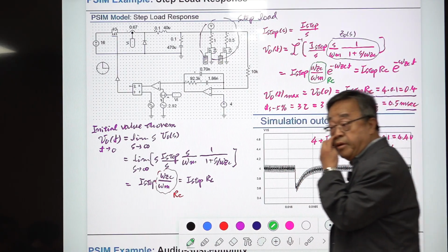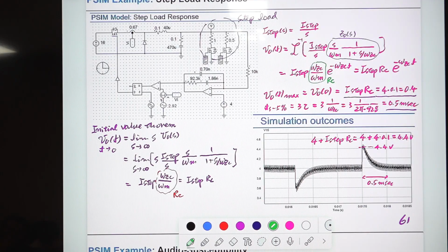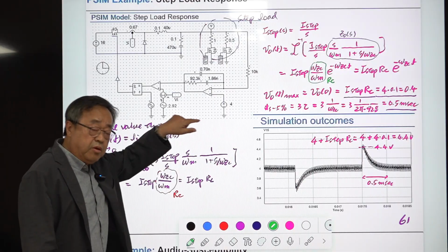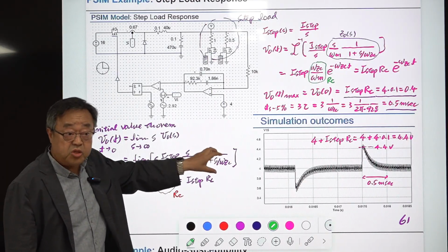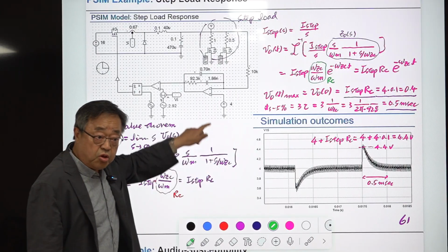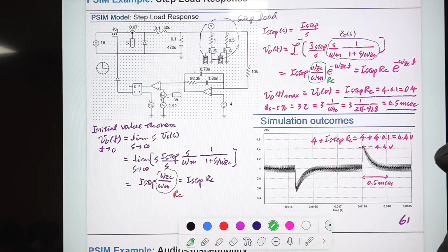So this is very special, because this simple linear analysis, the knowledge of linear time invariant systems, provides almost exact information about this nonlinear PWM converter, because we have a small signal model and the tools, asymptotic analysis and so on, and design tools, everything is there. Okay, so with this you can predict the accurate behavior of this one.